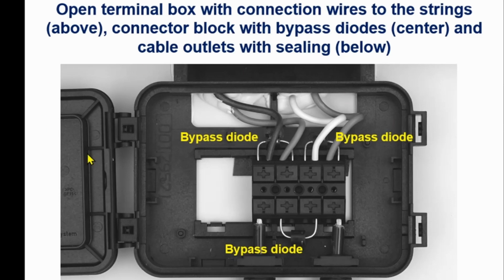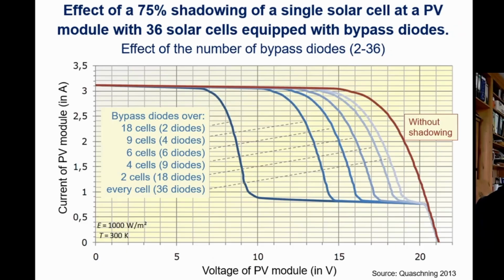So we have a solar module, a solar matrix. We have a string going to the lower part of the module and then another string coming back. These arrive here and we just bypass these 2 strings with this bypass diode. Same for here. So the outer 2 strings and here the middle 2 strings are bypassed by this bypass diode. So this module consists of 6 strings and 3 bypass diodes.